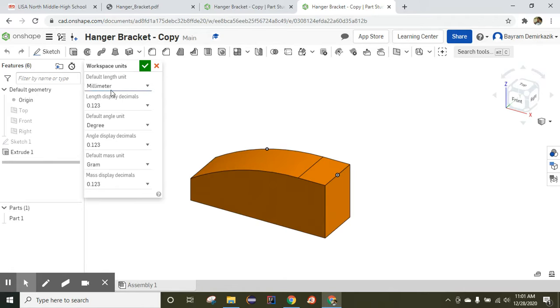If it is different with you, then you just need to change it to counter bore, and you can get all the information from here. Counter bore, ANSI inch clearance 8, the size is 8, and condition blind and 20 millimeter depth.